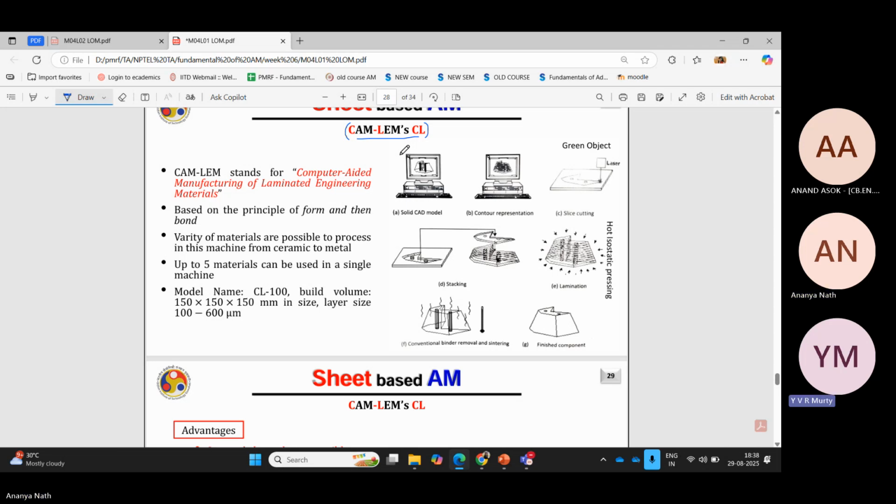There it is mentioned as hot isostatic pressing. Hot isostatic pressing is a very costly thing. Yeah, that is what is mentioned in the slide. Hot isostatic pressing is one type of sintering, and if they are demanding it, then they are selling the other part of the machine where you can perform this sintering operation. But obviously, it's ceramic and the layer thickness is very small, so the part size will be small. That's why the machine will not be very big, but it's a two-part machine.